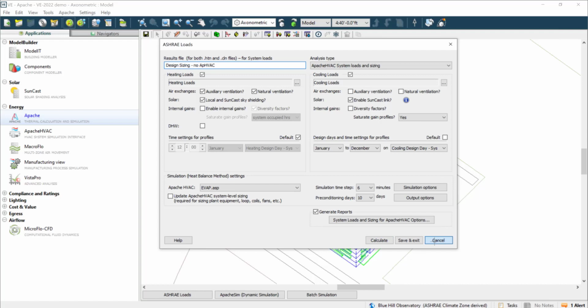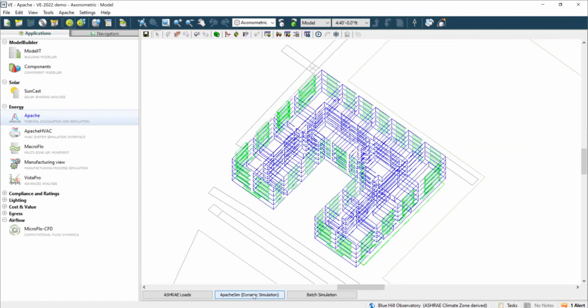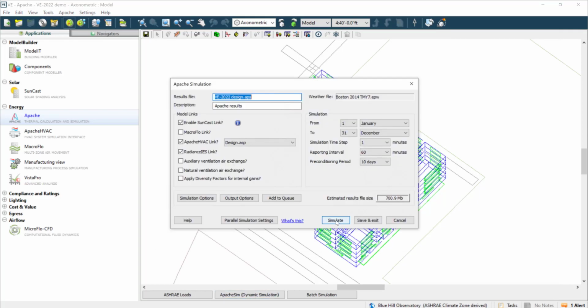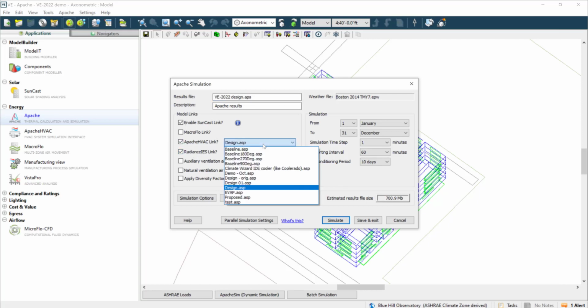Or you can do energy simulation. That one's much more detailed, same span, but this simulation is happening every minute of every day of the entire year. So that's why the simulation results are a lot larger here. It's over 700 megabits. And this is taking in simulation data from the solar simulation tool, the daylight simulation tool, and you can even look at a range of HVAC system options, which is my next topic.